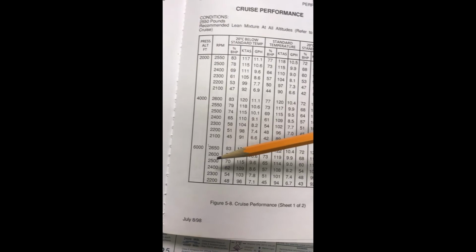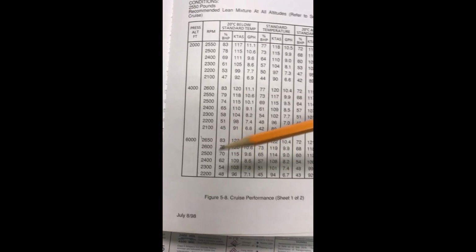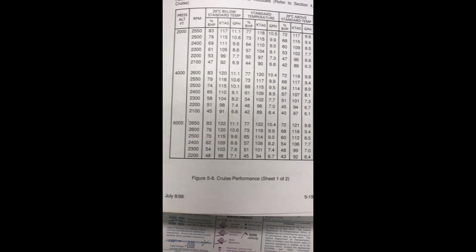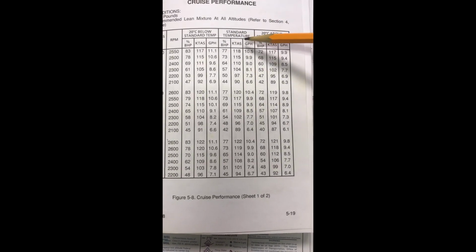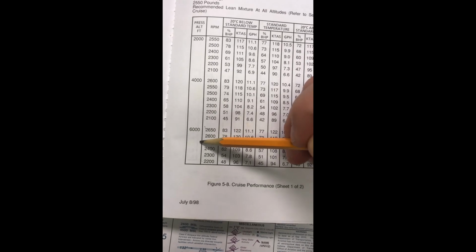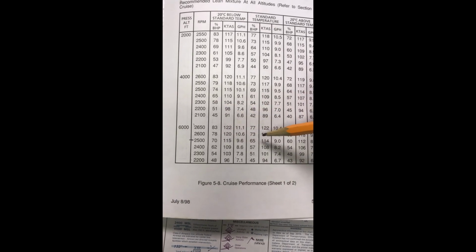This chart is given to you in pressure altitude, so we do have the opportunity for a little interpolation here. We'll just go ahead and get some approximate values. 5,500 feet, pretty close to 6,000 feet. We're going to make sure we reference the standard temperature block here. And we're going to go ahead and say that we're going to use about 2,500 RPM. We don't want to use a high-speed cruise regime because it's going to be less efficient, but we also don't want to fly too awfully slow.